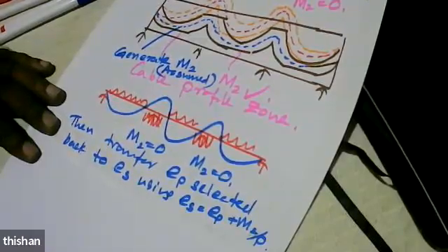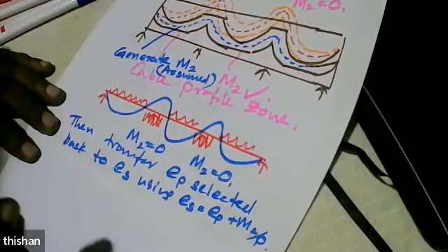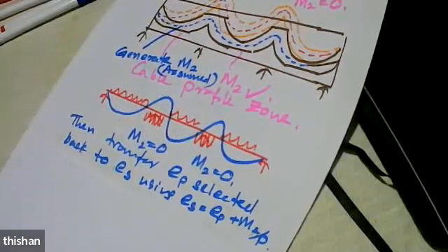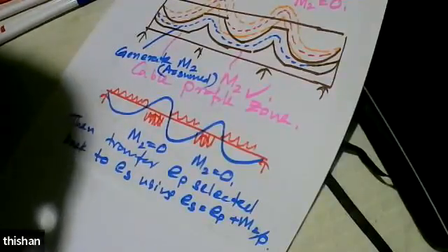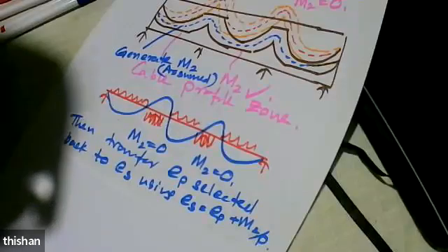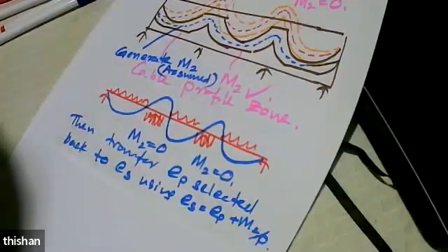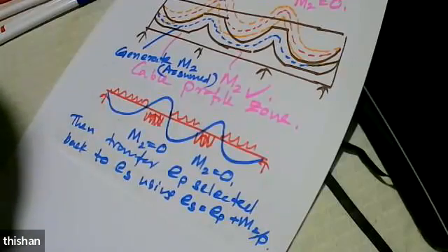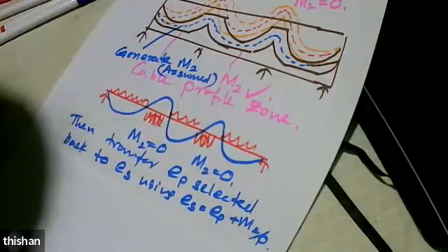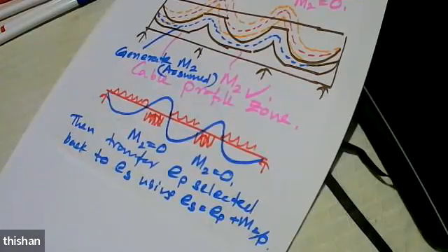Using this method you can very easily design a continuous beam, and because there are so many sections involved, now we have put it onto a spreadsheet. By using a spreadsheet, we can show how this can be done numerically. But the important thing is to understand the theory. The theory is that there's something called linear transformation, which you can find in any textbook.